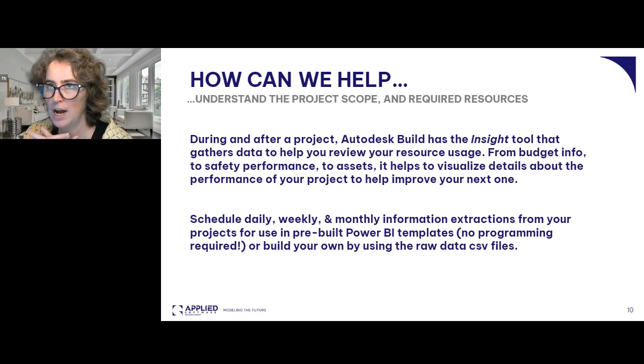So now, aside from that, Build has something called an Insight tool, and this is where all of the data I've been talking about so far is being gathered and translated into data that you can read. So it's not just all of the granular data, right, in these Excel sheets or CSV files. We need it to be visible. And so there's scheduling data extraction tools that we can schedule so that every Friday at 5:00 a.m. something is generated, and so Monday morning I have all of the latest updated data about any given projects that I'm working on, and I can move forwards using that data.